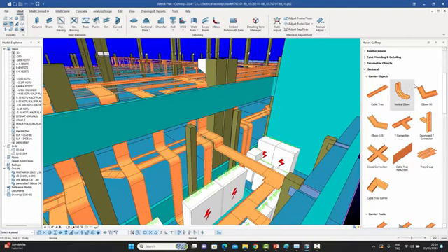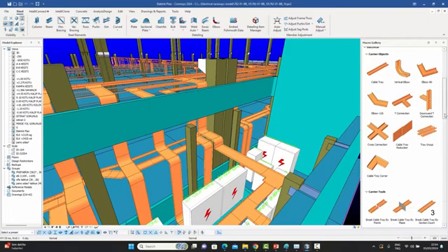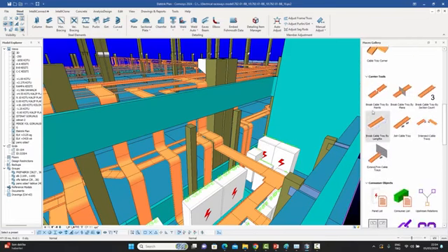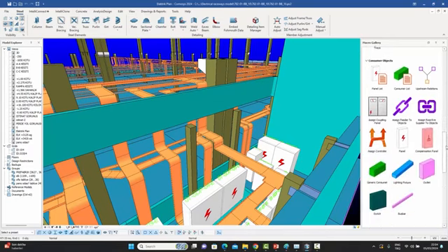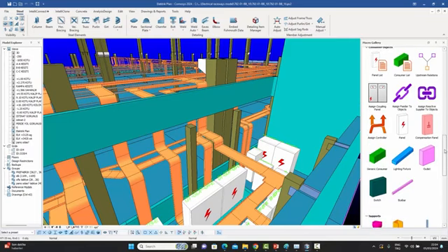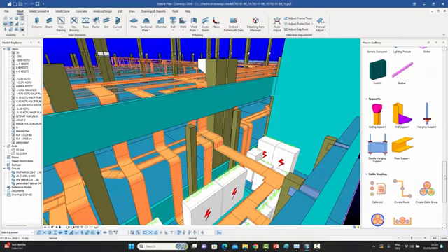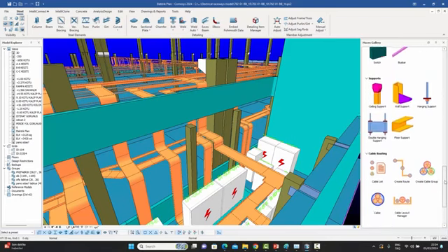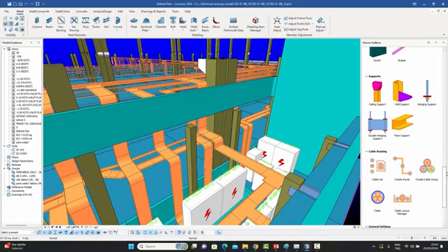You can see on the right-hand side that we have commands for creating cable trays, the vertical elbows, 90-degree elbows, specialized elbows, T connections, downward connections, cross connections, basically anything you will need to model your cable trays, and then to modify them by breaking them or joining them or mitering them, etc. And then we have consumer objects to create panels and consumers and all the electrical consumers which you might have, lighting fixtures, etc. And then you have even some support macros for creating supports for these cable trays, because they need to be connected to the steel structure or the concrete structure.